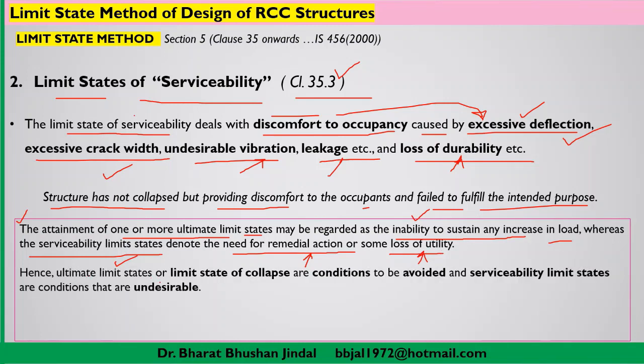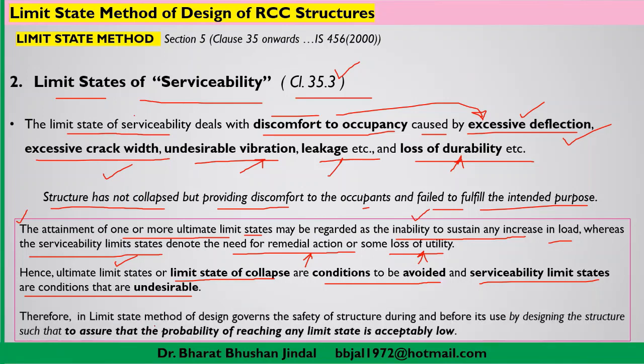Therefore, the ultimate limit state or limit state of collapse are conditions to be avoided during design, and serviceability limit states are the conditions that are undesirable. Therefore, in the limit state method of design, we are governing the safety of the structure during and before its use by making sure that the probability of reaching any limit state is acceptably low.